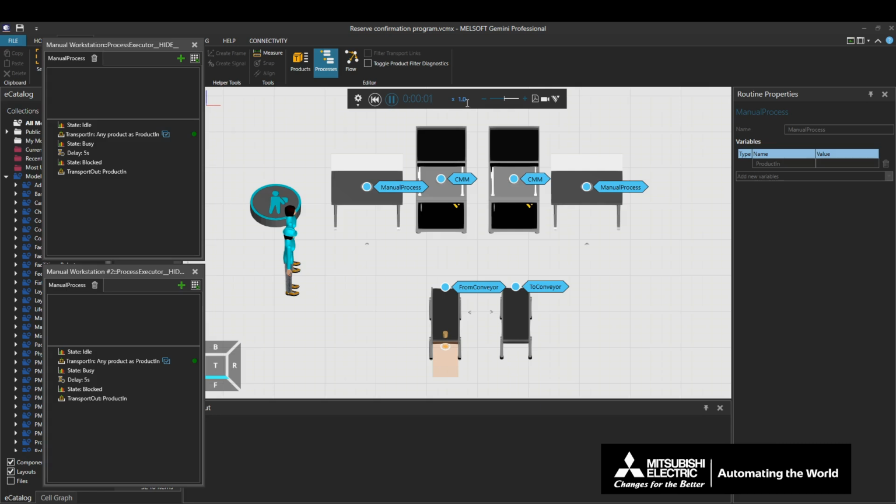When the resource temporarily cannot be allocated a task due to the delay statement, other process tasks can be allocated to the controller. When this happens, the order of statement execution may be affected because the other process statement tasks are executed while the same process statements are being executed. To make a resource execute only the specified process statement tasks, use the Transport Controller Reserve Resource.